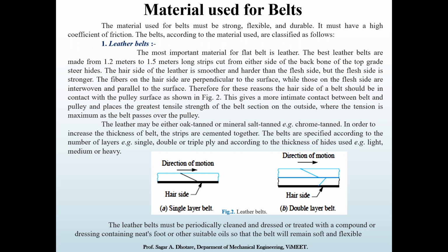If we want to transfer a heavy load, we need to go for multiple ply. The leather belt must be periodically cleaned and dressed or treated with a compound and dressing containing neat's-foot oil or another suitable oil so that the belt remains soft and flexible.